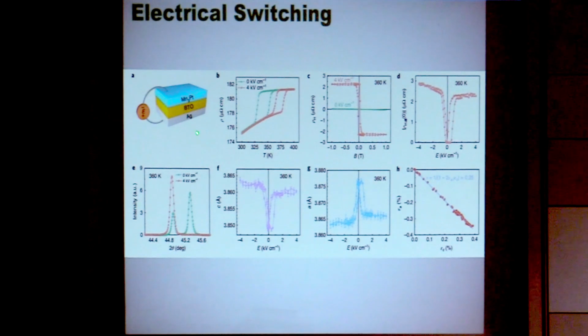Now in this kind of multiferroic heterostructure, again we do the same thing as with iron rhodium. We use the piezoelectric strain to try to modulate the phase transition temperature of the first-order phase transition of this Mn3Pt. Initially, around here, this point is already the collinear phase, so there's no anomalous Hall effect. But if we apply an electric field to this stack, the piezoelectric strain generated from the barium titanate will be exerted on this thin film, its lattice is compressed, and the phase transition temperature is enhanced by about 20 K, and then it moves from here to here. This now becomes the so-called non-collinear phase.